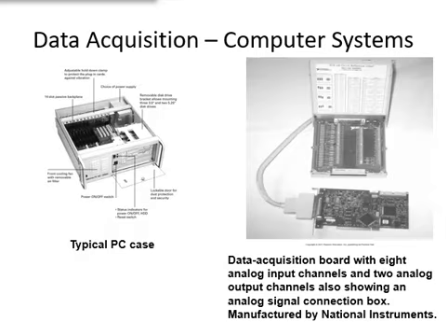The computer system most commonly used for data acquisition in experiments is the personal computer using the Windows operating system. Sampling rates of over 10 million samples per second are possible, and more than 3,000 separate sensors can be sampled, although not in the same system at the same time. Several major companies supply software and hardware to make a personal computer into a data acquisition system, and some of the hardware is available in low-cost generic form.